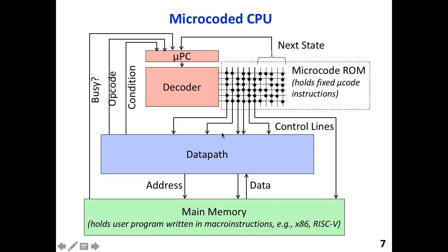So the finite state machine, that is the instruction fetch, instruction decode, instruction execute, and then instruction store, that is a four-step finite state machine, which can have many different instructions, and all of that gets microcode programmed into the read-only memory. And if you remember your finite state machine design, you'll remember that there is combinational logic. Well, this is part of the combinational logic. That's a lookup table. And so that'll get you to do the next instruction and describe how that gets executed.